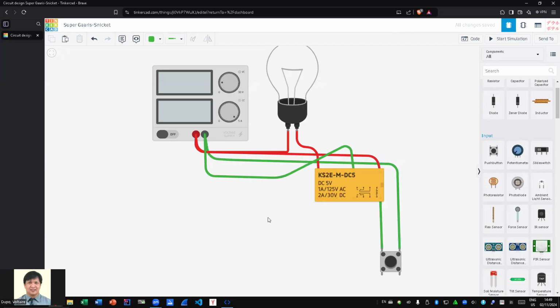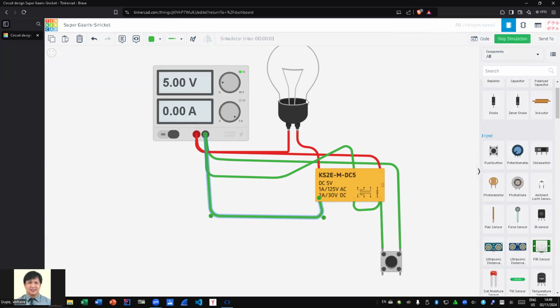Okay. So when we now go into using a relay contact as another means to latch the circuit, this is what we mean. We imply now that we can take part of the coil inputs that we have towards this interconnection that we have here. So part of the coil input will now be sequenced towards that one and sequenced towards this end. So when you originally turn it on, it's not on.